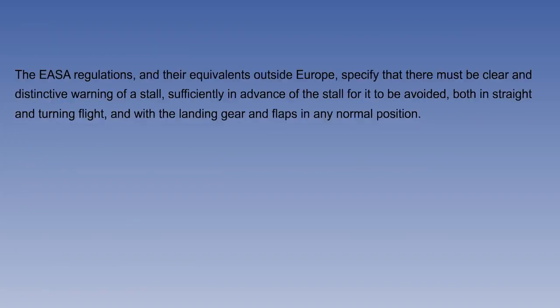The EASA regulations and their equivalents outside Europe specify that there must be clear and distinctive warning of a stall, sufficiently in advance of the stall for it to be avoided, both in straight and turning flight, and with the landing gear and flaps in any normal position.